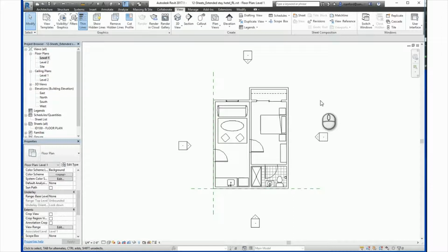Using sheets in Revit makes it possible to accurately document a design project. Views of the model are placed on sheets in order to create a drawing set for the project, which then can be plotted. Sheets usually contain a title block and are accessible from the project browser. Everything you find in a typical drawing set and more can be conveniently placed on a sheet: plans, sections, elevations, 3D views, schedules, text, and images. Actually, all views in a project can be placed on a sheet.